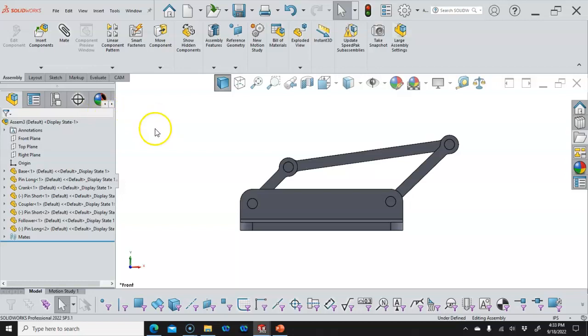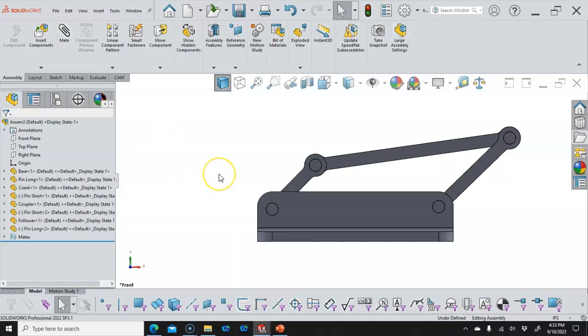But on the configuration side, or when we go into the drawing and make an alternate position for this piece, then it will create a configuration for us and we will pick another location so we can show the limits of travel or some of the method. So the takeaway is we're going to put these in position coincident for our planar surfaces, concentric, and occasionally throw in a parallel or an angle or distance dimension.